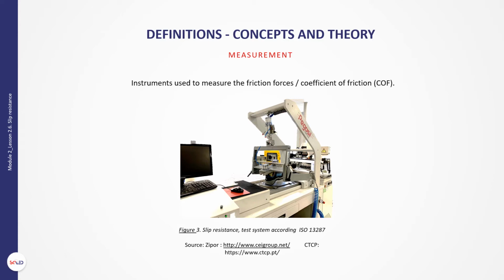The classic laws of friction state that COF is independent of contact area and velocity, however these laws are not obeyed by viscoelastic materials like the synthetic polymers used in most shoe outsoles. In the presence of these polymers, the parameters of peak force, loading rate, pressure, and time of contact between the instrument test foot or shoe and test surface influence the COF values, and these parameters may diverge widely using different instrument types. To be compared, the COF values need to be associated with a specific calibrated instrument type, test foot material, and test method.